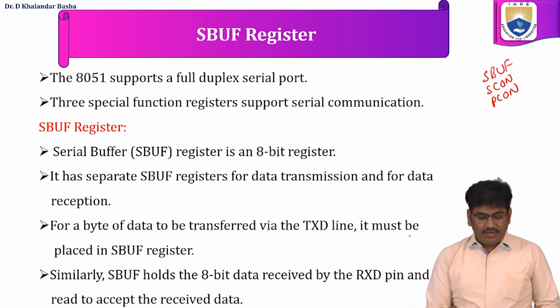SBUF register. The serial buffer SBUF register is an 8-bit register. It has separate SBUF registers for data transmission and for data reception. For a byte of data to be transmitted via the TxD line, first the 8051 microcontroller will copy the data into SBUF.